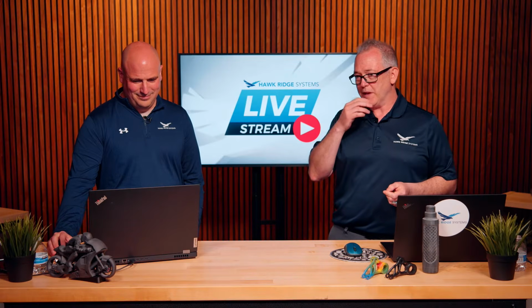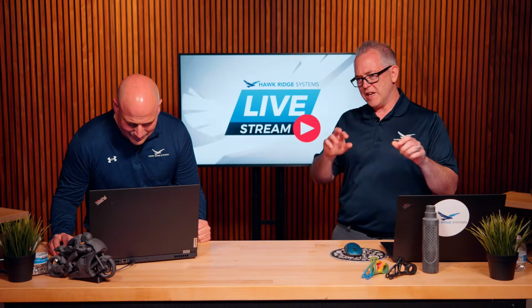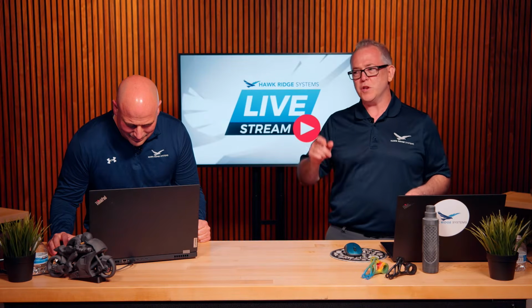Do we have time for me to add a little bit to that? Sure. Okay, cool. I showed this last year, and as we were talking, it rang a bell. Things like these fillets. If you've ever used the delete body feature, you can use that 1,000 times in your tree. As you're designing, you can say, "I have all these surfaces and I want to delete them," and you add a feature. Then you're designing more, and you have extra surface bodies, and you use it again. That is a great tool, and you can use it that way, but it's not the best practice.